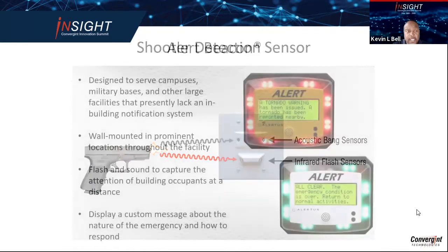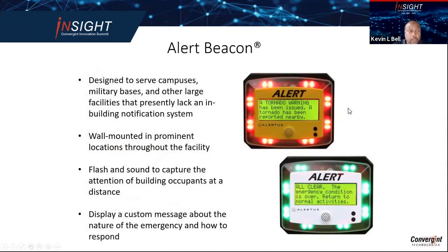The beacons that I mentioned will send text messages, and as I said, Cat5 with PoE off of a switch is all that's needed. So there is not a lot of wiring and disruption to deploy this in your facility. And there's a piezo alarm here that has a 91 dB piercing alert that gets everyone's attention, along with the strobing LEDs. Set it up in whatever color you want. And this gets everyone's attention.